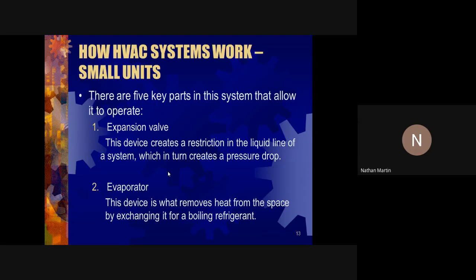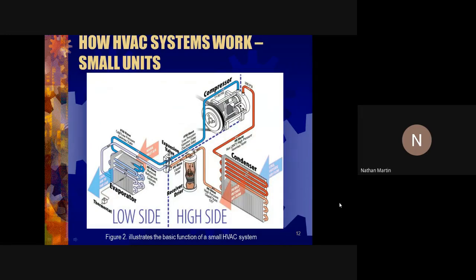So it is the part of the system, and that is why the line is drawn here, that determines the type of pressure: inside the car you'll have a low pressure, and outside in the system you'll have a build-up of high pressure to move the refrigerant around the system. Everybody can see why it has high pressure, because we have the output from the compressor here, and the compressor is pumping along the system.